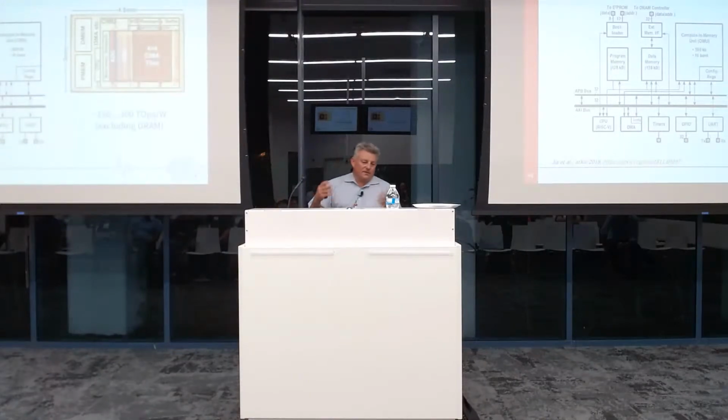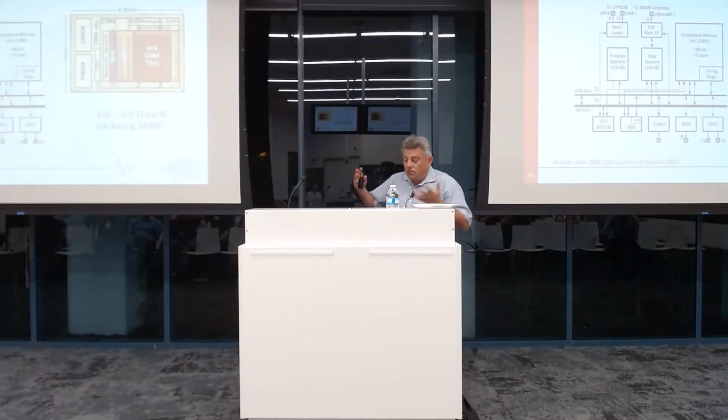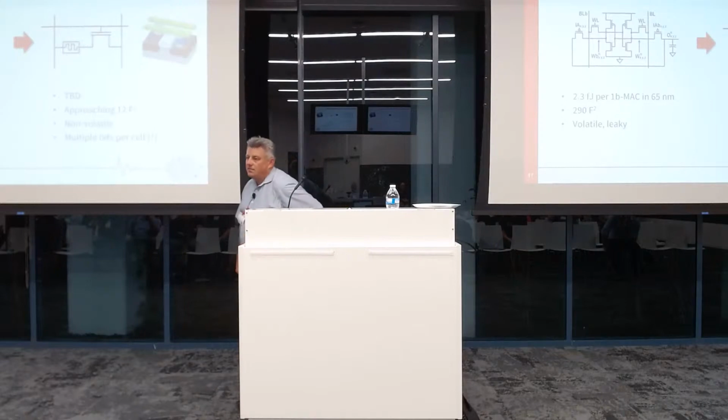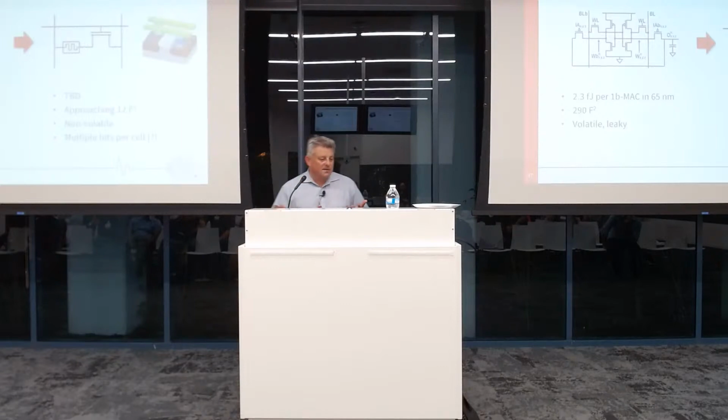So this is now one of these cases. Either you're going to make this chip much bigger and you get all memory on chip and somehow eliminate the DRAM, or you will be stuck with the DRAM energy efficiency. So how would you go about getting more memory on chip? And this is really where my research comes in now. To me, this SRAM compute in memory is, from an academic perspective, a done deal. The industry should run with it, implement it, sell it, and move on with it. I'm not going to do more research on that because the concept is proven.